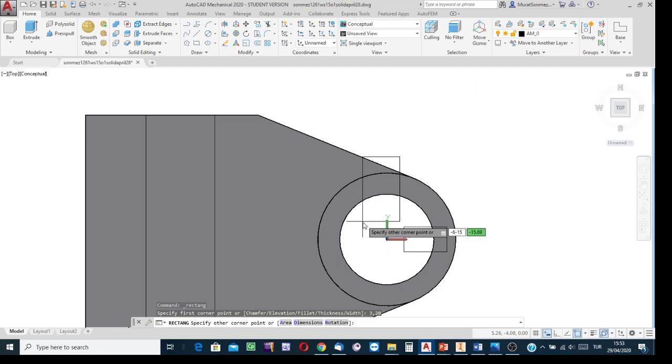Oh, sorry, I made a mistake. First, click on the comma key and then into the box write minus. It is negative because this corner relative to the first is in the negative direction of the y-axis. Yes, in AutoCAD, while direction is important, you need to pay greater attention. -15, 12, something like that. The y value is not so important, but the x value must be 6. Okay, and then the sketching stage is done.